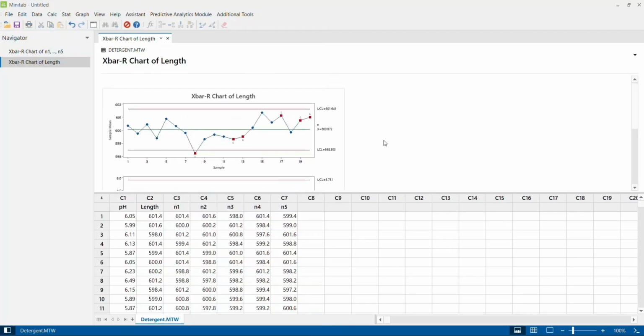So friends, let me summarize. This is the second control chart that we have seen in the series of control chart videos. Data type continuous, also called variable data. Sample is collected in the form of subgroup. What do we mean by subgroup? We need to logically decide a particular frequency as our subgroup. In our example, we have taken every hour as a subgroup, and in every hour we pick up 5 samples, so that becomes my subgroup size.